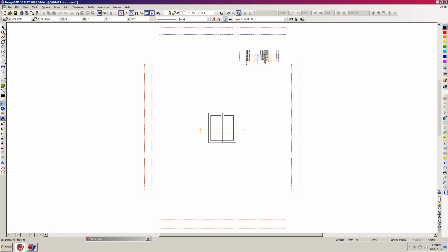So I'm going to right click close to this corner, and it snaps to the corner and sets a point. You can see that there's a point set down here, and then I bring my cursor on down to the floor elevation and just hit K, and it snaps to that line, and hit enter, and I have a line there. Now this is an awfully tall wall line, but it aligns with that front outside edge of the wall. So now what I'm going to do is select that line.